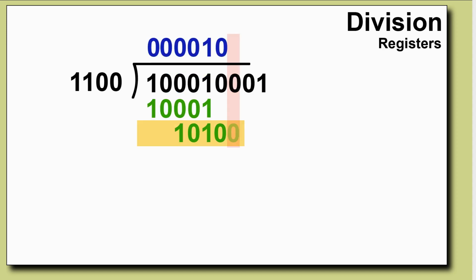Now, before we try and translate this to program code, I just want to talk a little bit about register assignment. Now, I've spoken about wanting to do a 16-bit divided by 8-bit operation. And the reason for that is a lot of the numbers we're going to want to divide by will be 8 bits. And 8 bits are the largest register we've got.